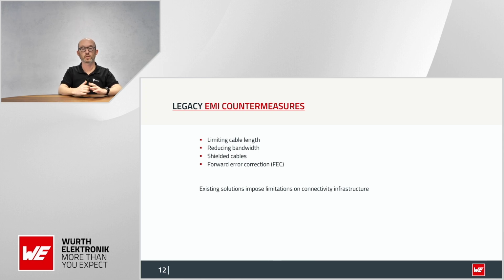When the signal-to-noise ratio gets worse because the narrowband interference is present all the time, we have a high probability of the radio emissions, and so this would mean we would need to add more and more redundancy to compensate, and this has a severe impact on the possible data throughput.